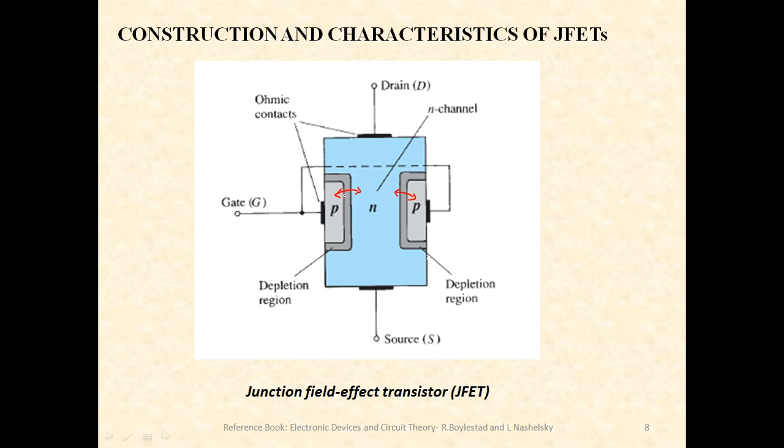So whenever we say PN junction, then obviously there should be a depletion region present, which consists of acceptor as well as donor ions. Okay, so that's the depletion region present. Okay, fine. Right now the JFET is not biased. The moment we bias, the current starts to flow through the JFET. Okay, so let us just go through the next diagram.